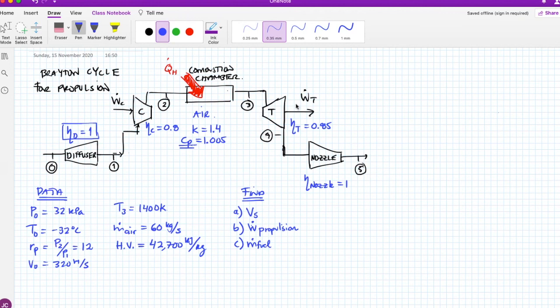Now, if you remember, this is worked out as an ideal gas, therefore we have the k and we have the CP. This CP, we also need to take into consideration that it's assumed to be constant along all the states, 0, 1, 2, 3. Actually, the thermal capacity has some dependence on temperature. So if you are changing the temperatures, the value of this thermal capacity at constant pressure should be changing.